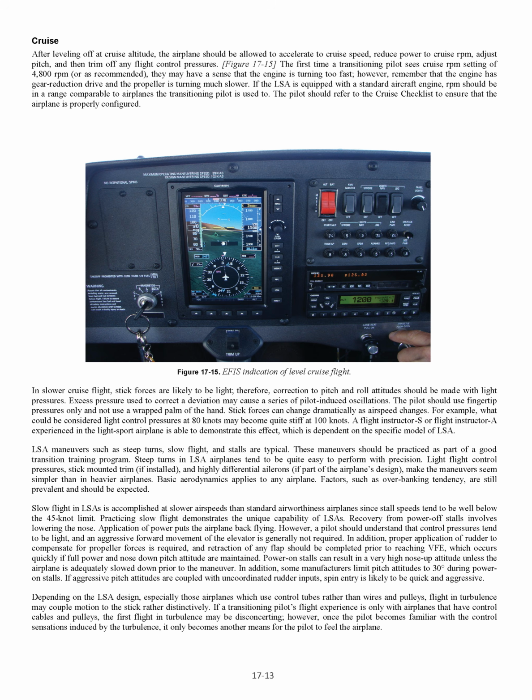Slow flight in LSAs is accomplished at slower airspeeds than standard airworthiness airplanes since stall speeds tend to be well below the 45 knot limit. Practicing slow flight demonstrates the unique capability of LSAs. Recovery from power off stalls involves lowering the nose. Application of power puts the airplane back flying.